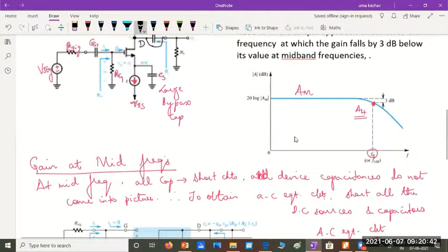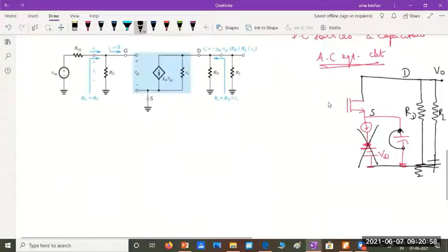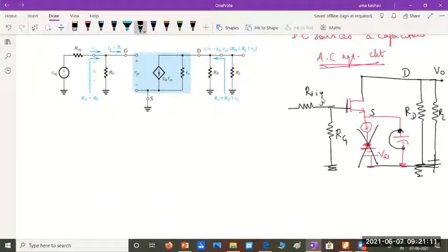And let's reproduce what we have on the input side correctly. On the input side, I have a resistance between gate and ground. This coupling capacitance acts like a short. So I'll just have to directly connect Vsig and Rsig. So here, we have Rg, the biasing gate resistance, and then I have Rsig and the voltage source Vsig. This would give us the AC equivalent circuit.